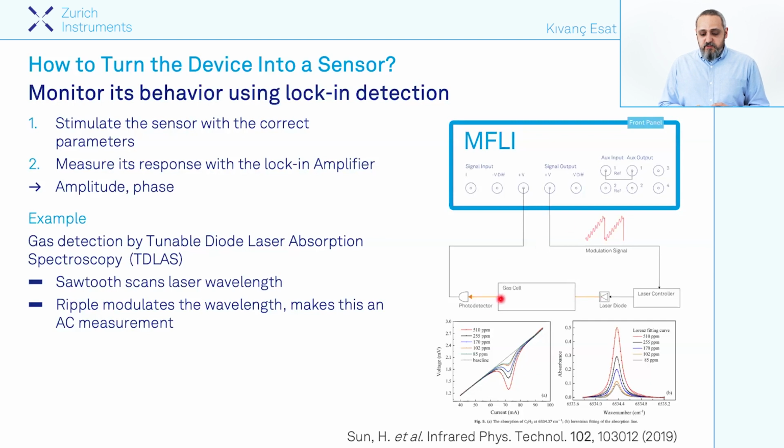A typical measurement would be, at a certain frequency, while we are moving around this edge of the sawtooth, we see a dip in the spectrum, and this corresponds to the absorption, right? And this we can depict as a spectral absorbance as well. This is one of the commonly used ways in gas detection. But let's look now at what other ways there are to enhance the sensor's response or precision. And with this, Jim, please take over.